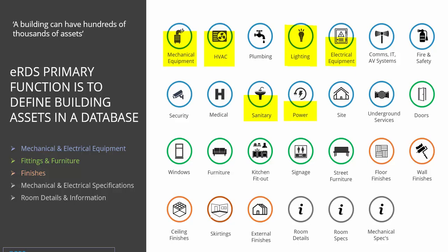From the architectural model, we can have more confidence that the doors and windows are correct in terms of numbers, types and their locations, and they are ready to be enriched with more complete asset information that will be required for FM. But as we see here, there is still a lot more to do to define and allocate approximately 70% of building assets that were not modelled as objects in Revit. We will show how this can be done in another video which we will post soon.